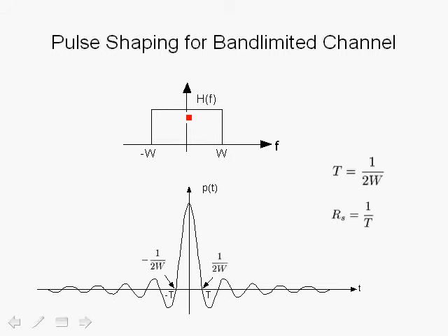Also, another property of the sinc function is that since we are limited in the frequency domain, we have a hard limit, this is a rectangle, then due to the nature of the inverse Fourier transform, the signal in the time domain will be unbounded, unlimited. So we see that by restricting the bandwidth in the frequency domain, in the time domain the signal is not time limited.